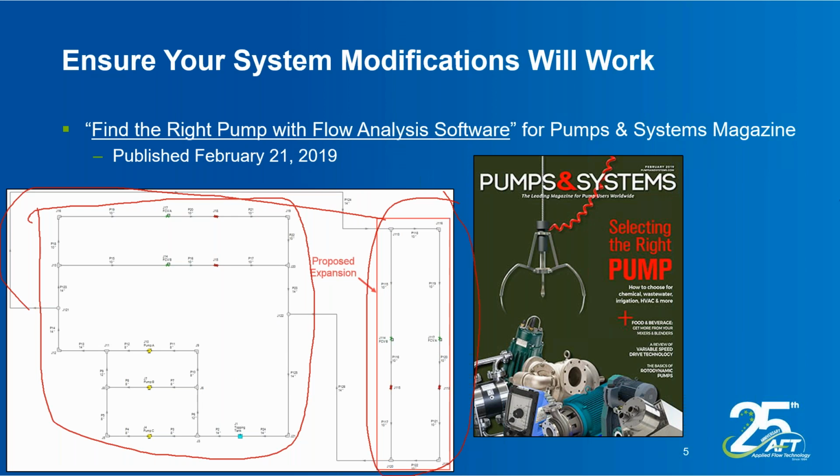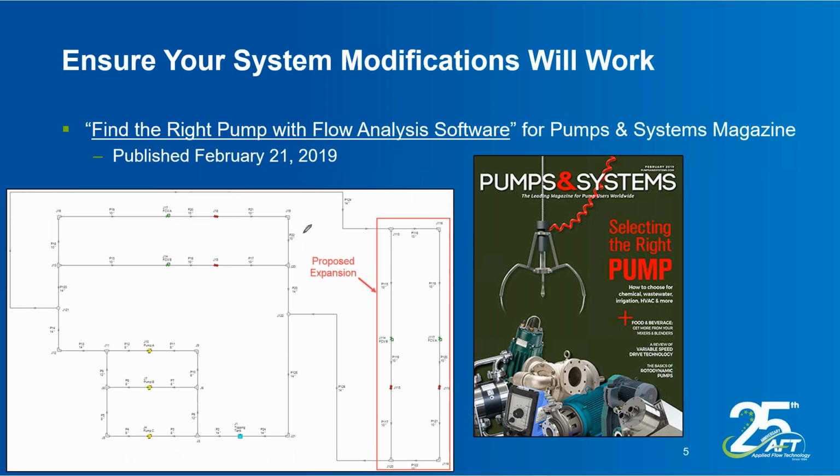You're going to have various design requirements. Maybe you've got some flow requirements to the heat exchangers. You might have certain velocity requirements. Control valves have to be able to maintain good control, so you might have a minimum pressure drop across the control valves that you want to be able to achieve. Maybe you want to ensure that you have plenty of NPSH for the pumps. All are different design requirements that you have to consider when you're designing your system, and you want to make sure those requirements are met.